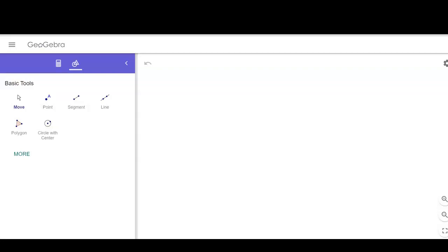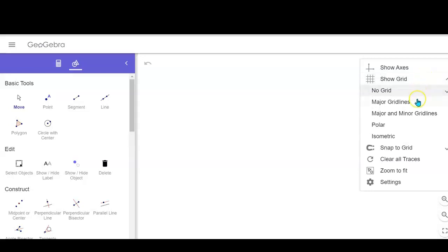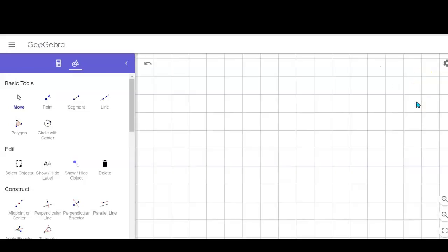We will first go to geogebra.com/geometry. On the right is the screen where we will be doing our drawing. On the left are a few basic tools. We will need more than these basic ones, so we first click on the box that says More Tools. It will also be nice to have some grid lines as a guide. Click on the Settings gear icon on the upper right-hand side of the screen, select Show Grid, and then select Major Grid Lines.